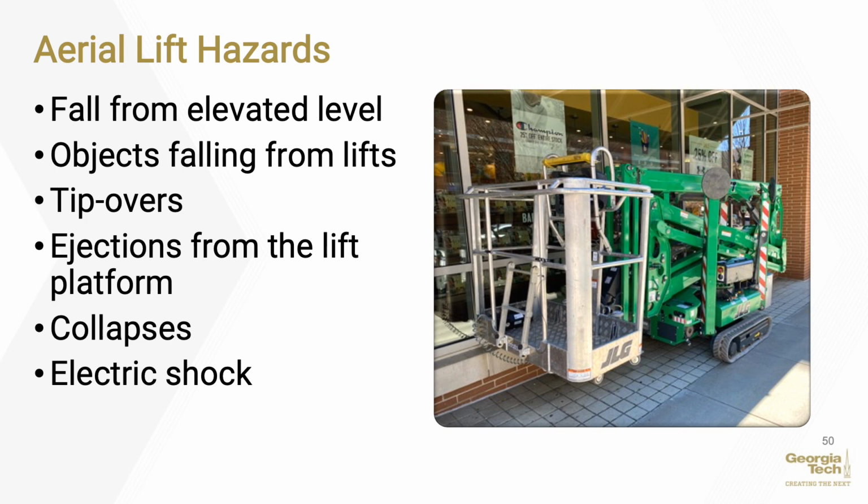The following hazards, among others, can lead to personal injury or death while using aerial lifts: fall from elevated level, objects falling from lifts, tip-overs, ejections from the lift platform, structural failures or collapses, electric shock or electrocutions, entanglement hazards, contact with objects, and contact with ceilings and other overhead objects.